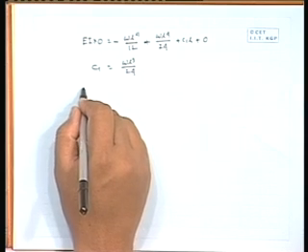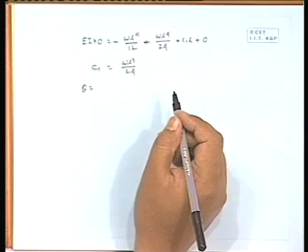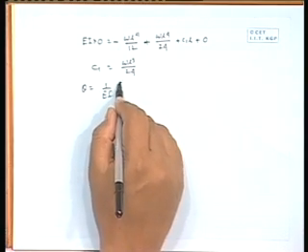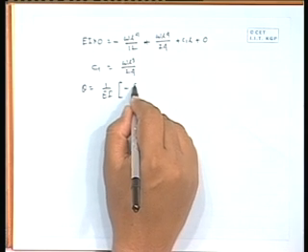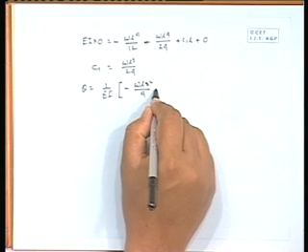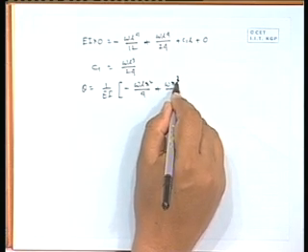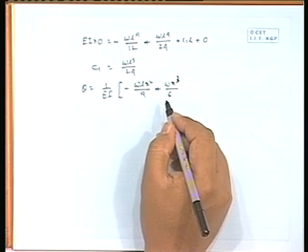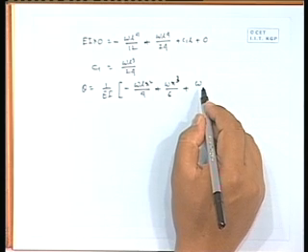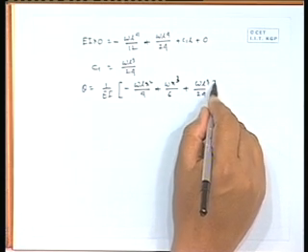So, we can write here theta is equal to, because from here already we have the expression, 1 by EI, and this part is minus omega L x square by 4 plus omega x cube divided by 6 plus C1, which is omega L cube divided by 24.